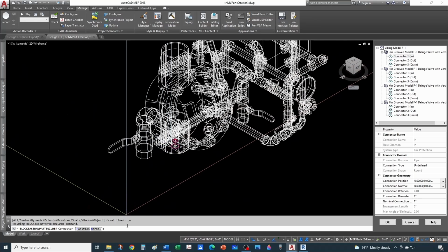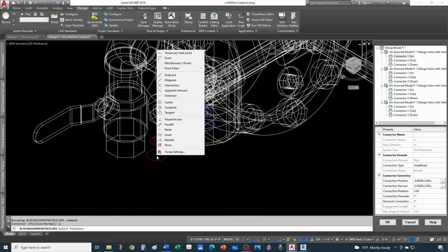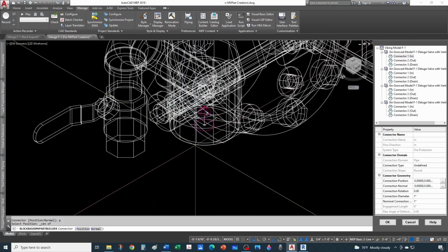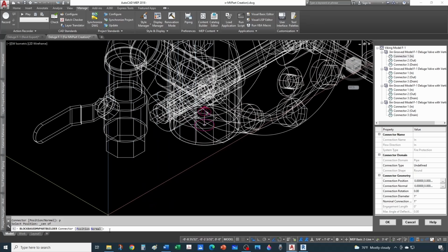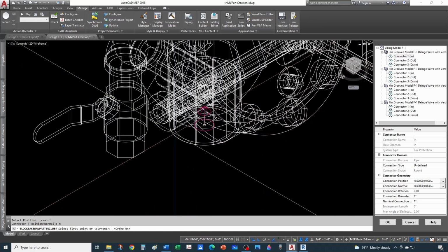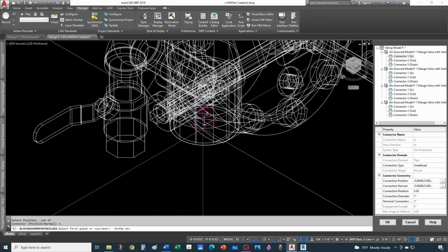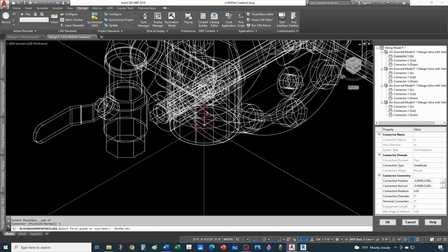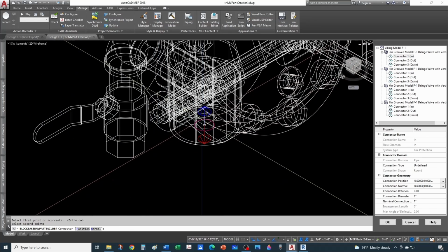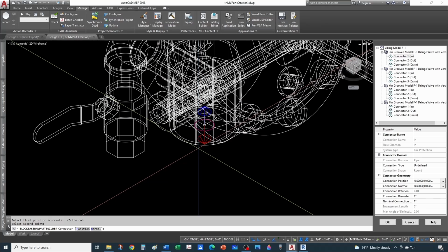And right now the position is in the correct position, but in general terms you would type P for position, then you would give it a position, right? It would be the center of this face, and then you would type N for normal, right? And I like to keep the ortho on, and then you just have to give it the direction. You don't have to touch specifically in the vector. You can click like here and here, you're just giving it the direction. You're specifying a direction. So that would be the N connector.